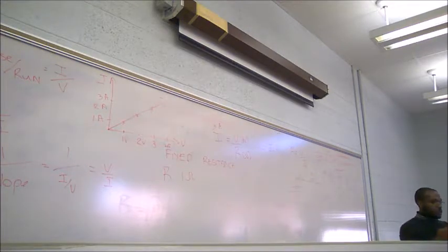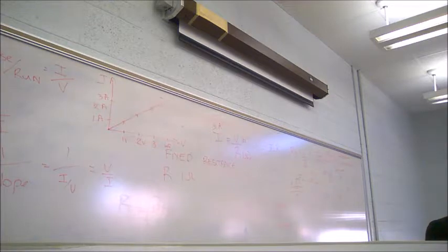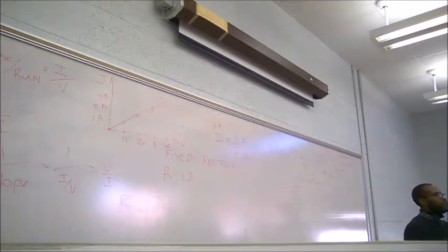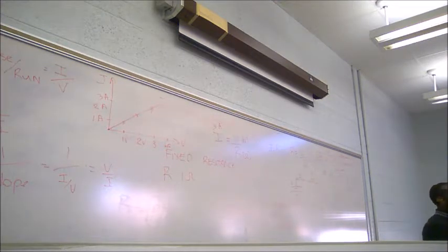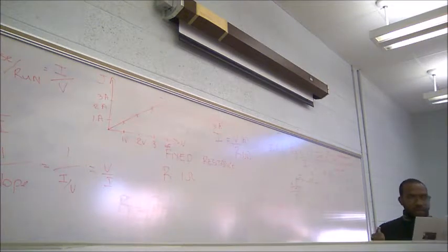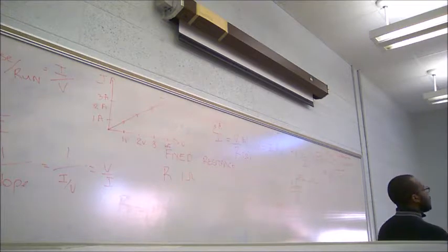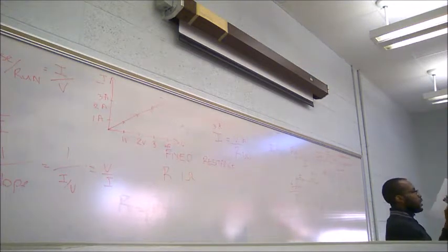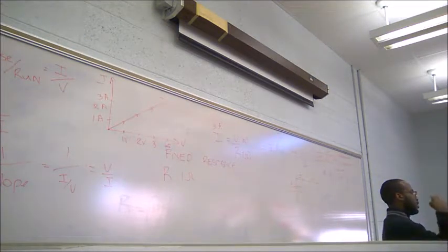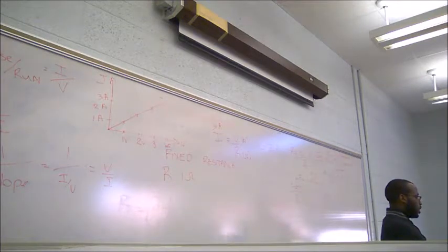Let's look at step number 2. I think we talked about all of this, so we're going to jump to step number 4. Everyone there? So after we take our three resistors, record the tolerance, calculate maximum and minimum, measure the resistance, and check whether it's in the tolerance range, we jump to step number 4, which says this test measures skin resistance. Like last time we talked about electricity, based on the skin resistance, it determines how much current enters our body.